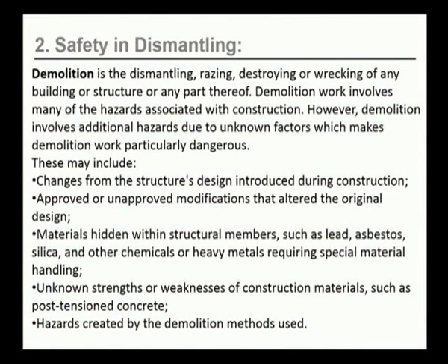These may include changes from the structure's design introduced during construction, approved or unapproved modifications that altered the original design, materials hidden within the structural members such as lead, asbestos, silica and other chemicals, or heavy metals which require specialized handling. It may also happen that radioactive materials may be inside a structure and we do not know. So, when we demolish that, we have to take specialized precautions. Unknown strengths or weaknesses of construction materials such as post-tension concrete, and hazards created by the demolition methods used.